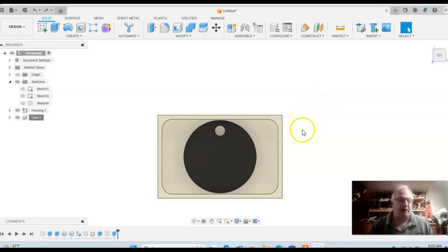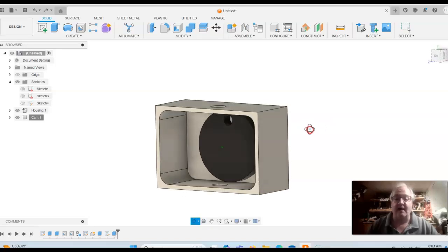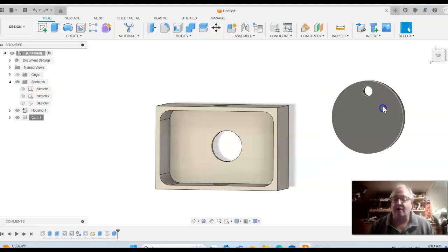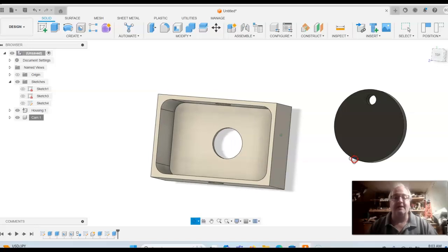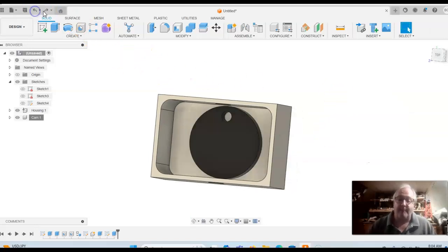All right, we are back for part two on the Scotch yoke mechanism. We're going to continue to build. In this case, I want to start. We ended the last video where we had created these two parts. Now, notice at this point they are still not really joined together. So let me hit the back and put that back in place. So we need to create a relationship between these two parts.